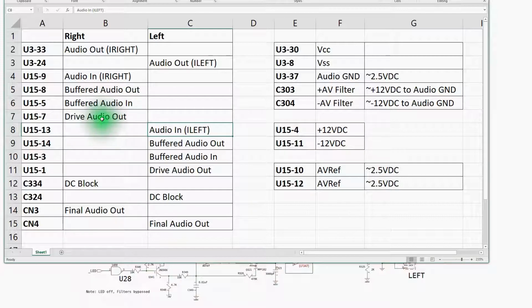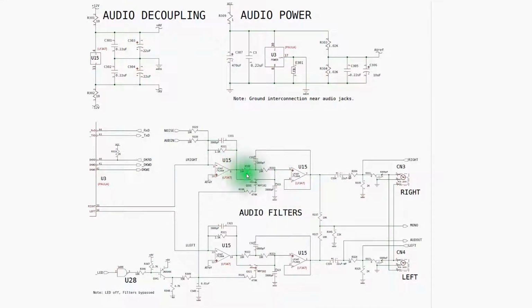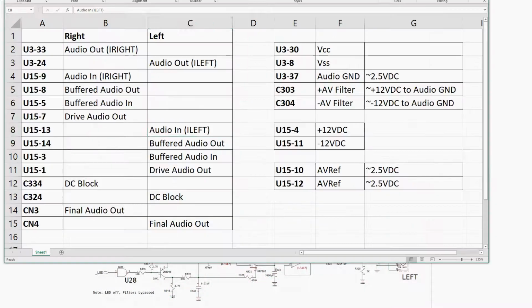But what this gives me is a quick list I can look down to follow along. So I can look at the list and look in the system, and I'm not looking at the PCB and coming back here and finding my next point in the schematic. I have a clear troubleshooting list to look at the major things in the system that will give me potentially good hints where the problem may lie.